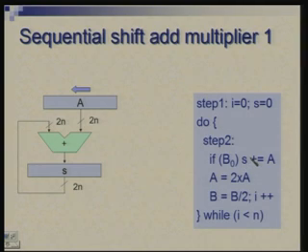And to take care of this, A will be shifted left. While A forms an input to this adder, A will also make itself ready for the next cycle. So, at the edge of the clock, S plus A is stored into S, and 2 A is stored into A. These two events will happen concurrently with the edge of the clock.